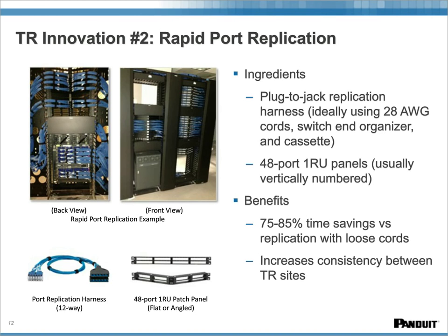Well, typically there is the running of the equipment cord from one side of the rack to the other. So typically there's a little more dressing required, and therefore the time savings is greater when the cords are bundled together. This also can increase the consistency between telecom room sites and make it very easy for installers to achieve a consistent implementation.